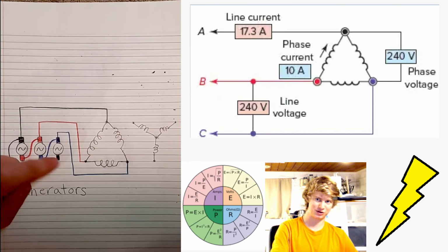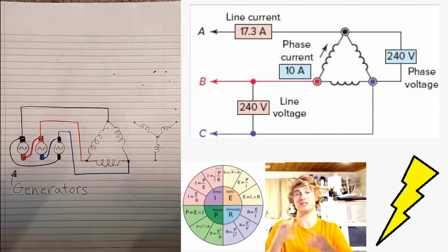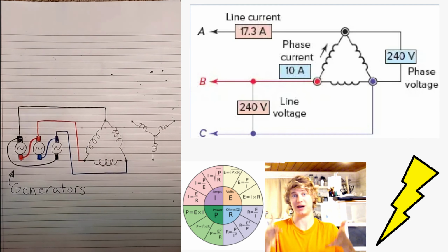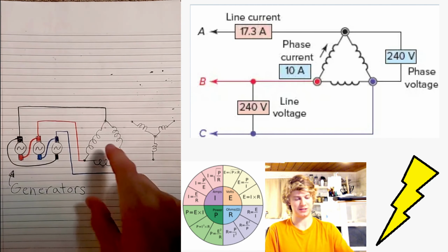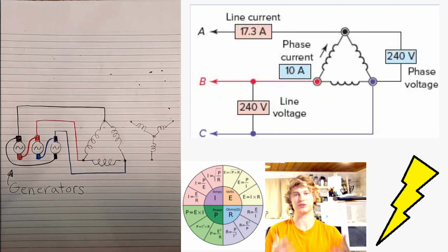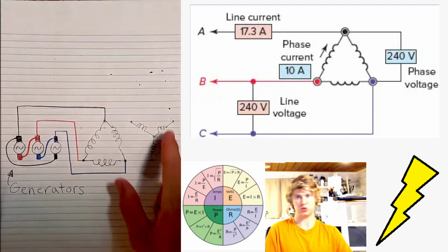So because everything is connected, you can see that all three of these generators could simultaneously send power to a load downstream. Okay, and now if you actually wanted to get a delta configuration and supply that to a house, let's say 120 volt lighting load, well, you couldn't do that because there is no center tap. While we see in a Y connection, we do see the center tap, which is going to help us understand how we could tap off 120 volts from this Y alternator.